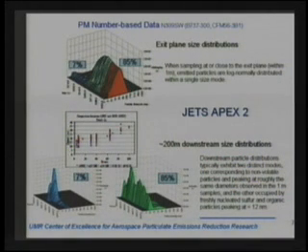So again, that's just re-emphasizing the point that I was making. If we compare the 1 meter, where we just have soot, we can see a small size distribution shifting to a bigger size distribution, lower numbers shifting to higher numbers. Things look very different when we include the volatile particles, which is really adding a significant amount, especially at idle, but even at higher powers where we have a lot of soot.